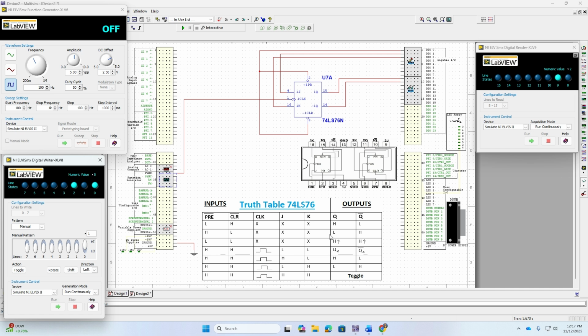Okay, and I'm going to show you a little bit of the truth table so you know what to expect. What you see up here with the preset and the clear, when we can actually set inputs into them, is where the preset is low and the clear is high. Ignore all these. Right now we're tying the preset and the clear together, so we're going to turn this into a toggle, almost like a T flip-flop. So you'll see down here at the truth table where the pre and the clear are both high, they're all high. So we're working with these last 4 rows of the operation of this particular JK flip-flop. So just focus on the last 4 rows down here.